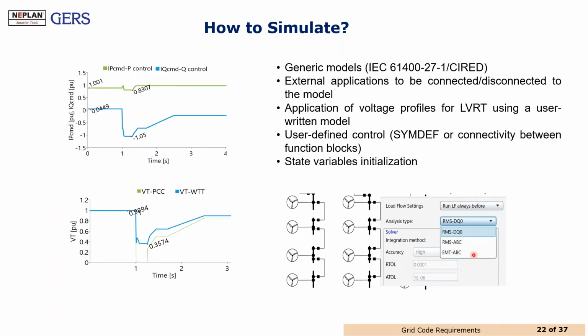In some specific cases, electromagnetic transient simulations are also required when the simulation in RMS is not enough to validate the oscillation of the frequency, and we have to check in the time domain of the instantaneous values what is the performance of the control systems, because in some cases the EMT simulations can present some behaviors that the simulation in RMS are not enough.